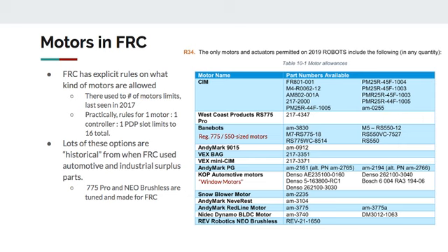In practice, what it means is that you can have as many motors as the number of places that you have to plug them in. Unlike in FTC, where you can put down another REV hub to get more motors, you cannot put another PDP on your robot. So 16 motors, take it or leave it. It's a lot for pretty much every situation, but you do still see some teams run into it. This year Madtown ran out of motors, partially because they do swerve drive, which takes 8 minimum, so they had to do a power takeoff for 2 of their mechanisms to get what they wanted.